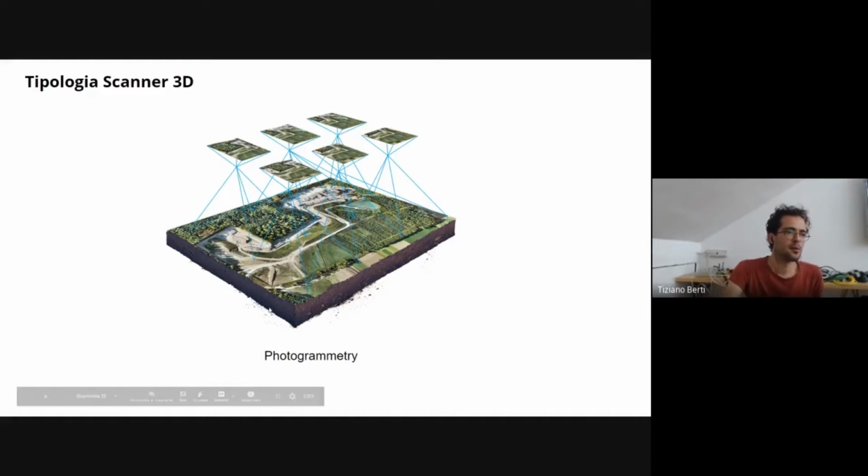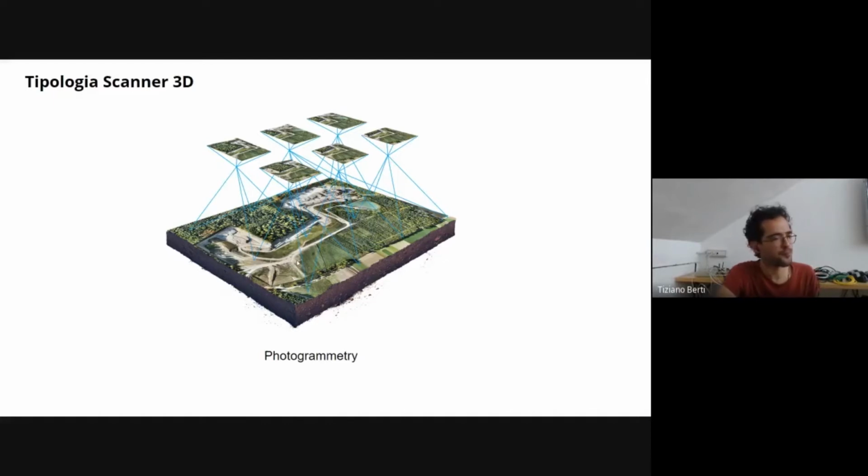And the other thing we were saying is we need a lot of texture in the photogrammetry dataset. So photogrammetry is really, really useful on natural objects. Like if I'm scanning a terrain, like in this situation, or a human body, I will have a lot of tiny features for the software to look at.